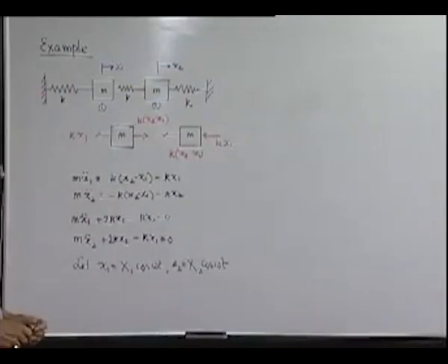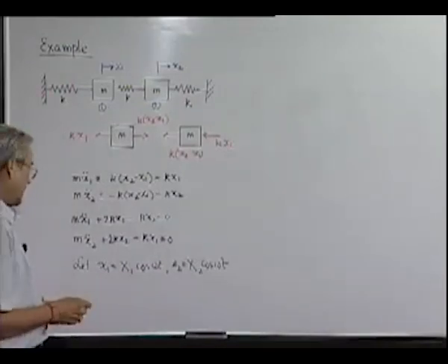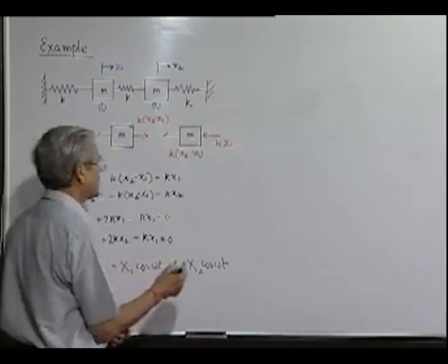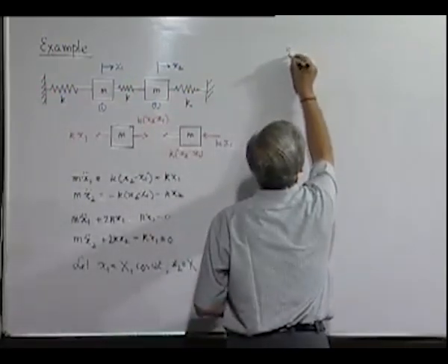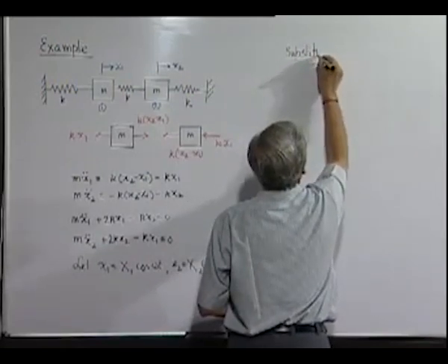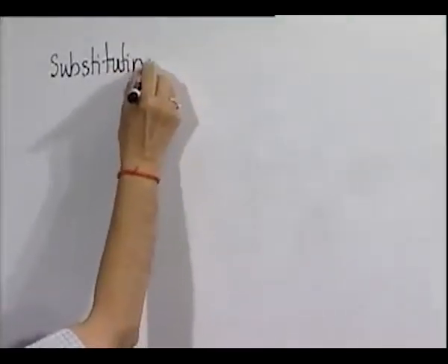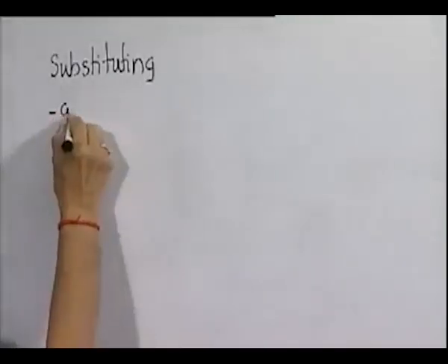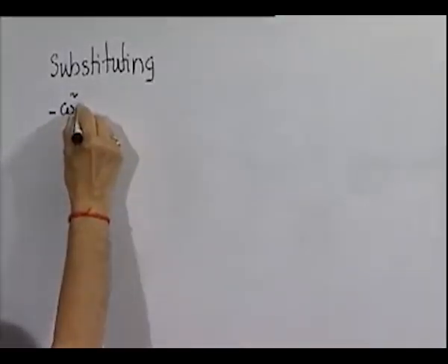As we know, in undamped situations, the motion can be either in phase or out of phase, and both can be taken care of by the algebraic sign of x1 and x2. If they are of the same sign, the motions of both bodies are in phase. If they are of opposite sign, then they are 180 degrees out of phase.